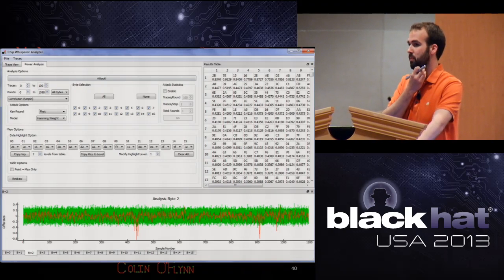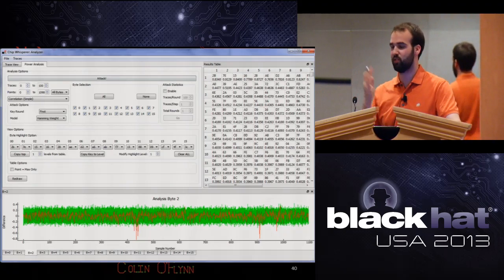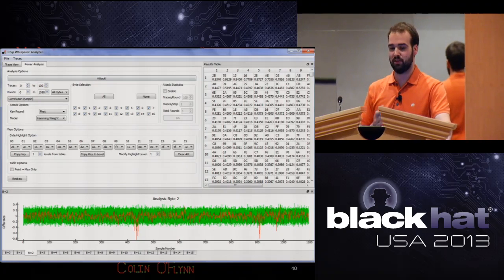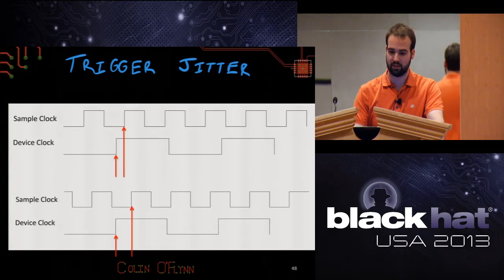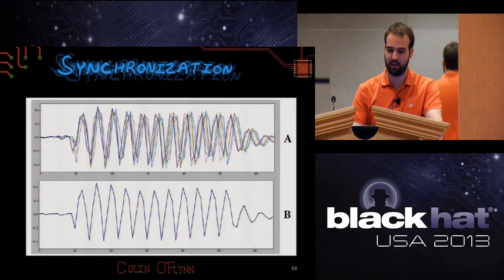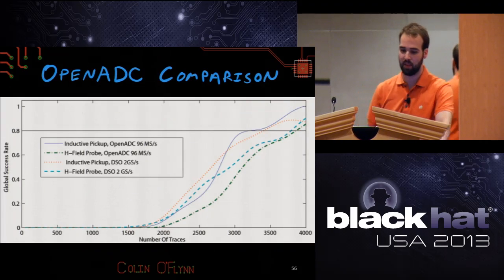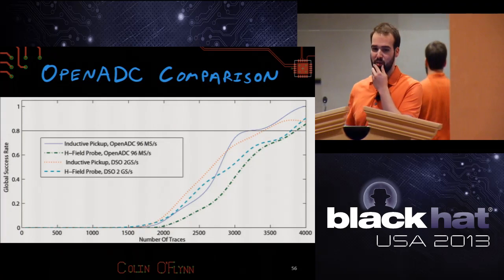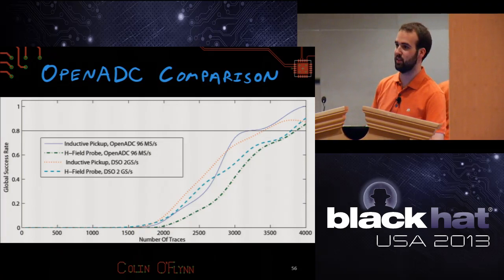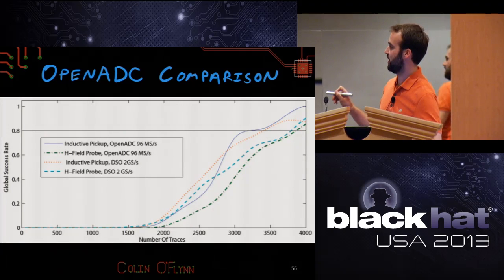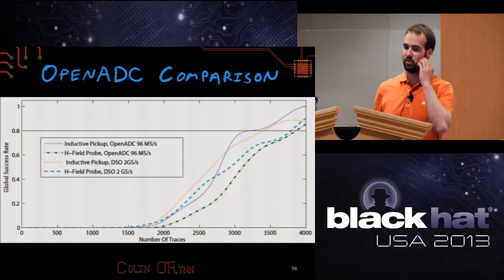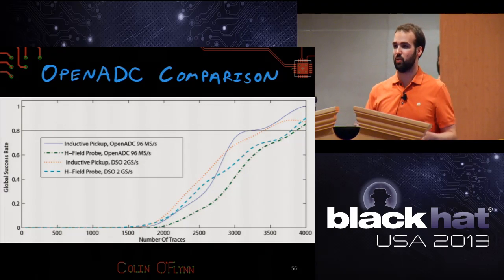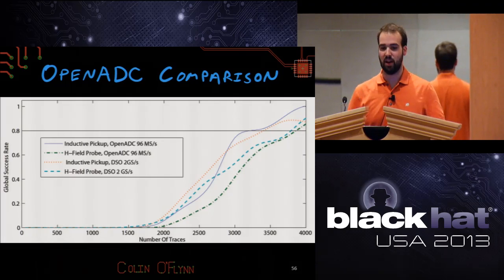Even if it's processing multiple bytes simultaneously? Yeah, so even if you do hardware AES and you do 128 bits at once, this works fine. So in particular, where is it? This slide here, I didn't actually talk about this. This is talking about against a hardware AES implementation. The hardware AES is running at 24 megahertz, and it takes 10 clock cycles to do a full AES, which means it's doing all 128 bits at once on every clock cycle.